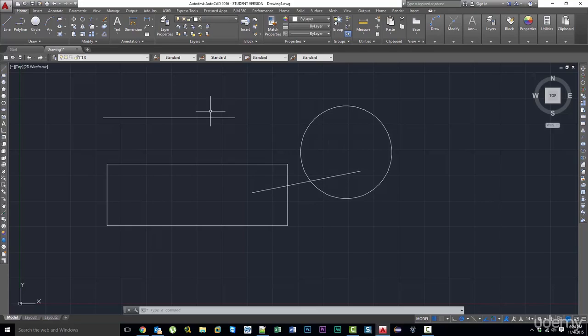For now, let's talk about snap points. If you look down here at this bottom toolbar, you've got something that says Show Snapping Reference Lines, Object Snap Tracking, and then you've got something next to that that says Snap Cursor to 2D Reference Points. And I've got both of those turned on. So let me click this arrow next to those two and see what these snap points actually are. And right there, wow, look at that.